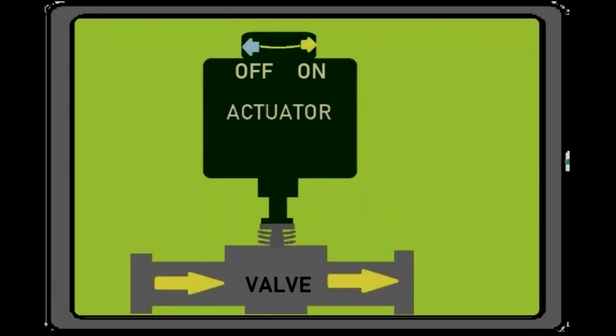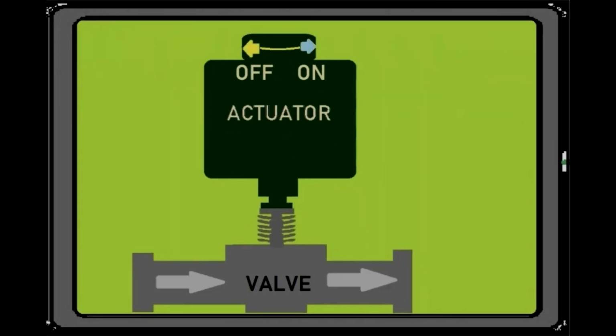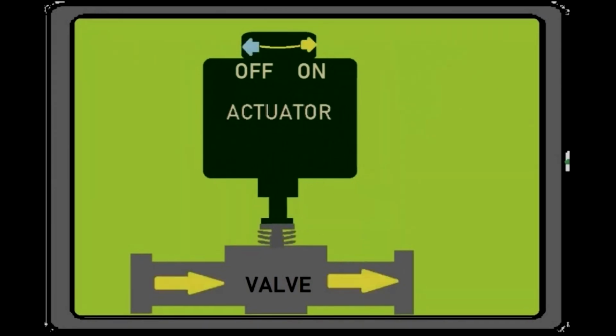To control the temperature and humidity, we use valves that allow the cooling or heating agent to pass by and heat or cool a heat exchanger. These actuators which are controlling the valves get instructions from a programmable logic controller, from a thermostat, or from a building management control.